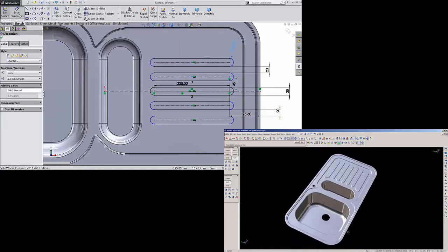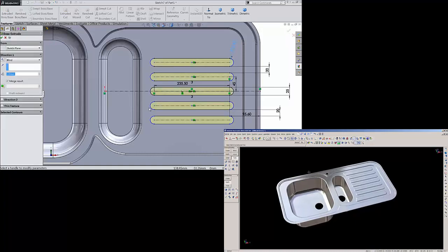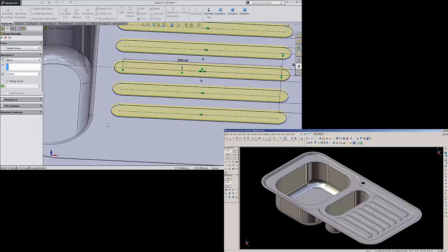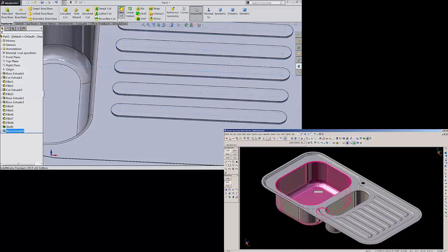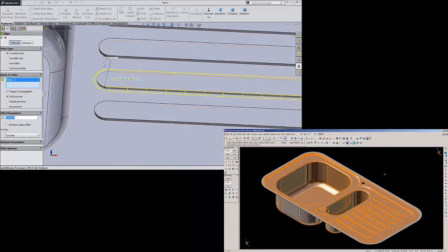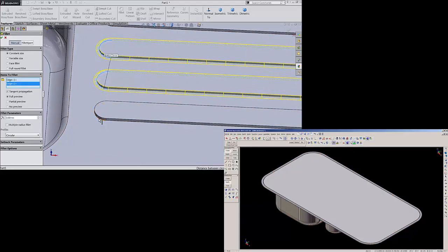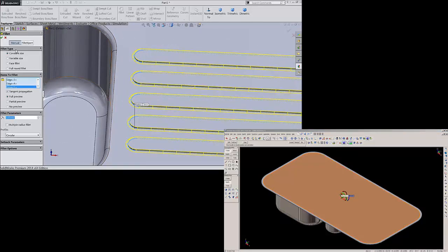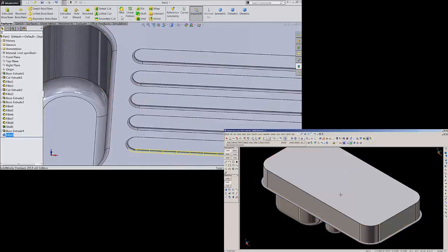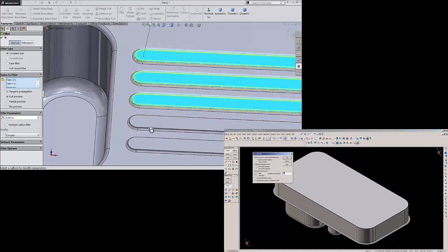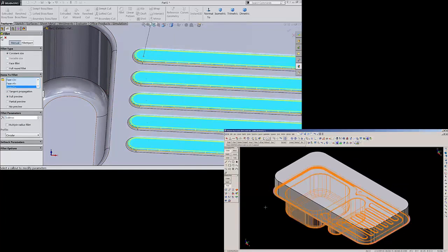Okay, now select extruded boss and extrude up to 3 mm only. Okay, choose fillet, keep 3 mm and select all these bottom edges. Okay, again keep fillet. Now this time select all these 5 top surfaces, keep 3 mm radius. Okay.